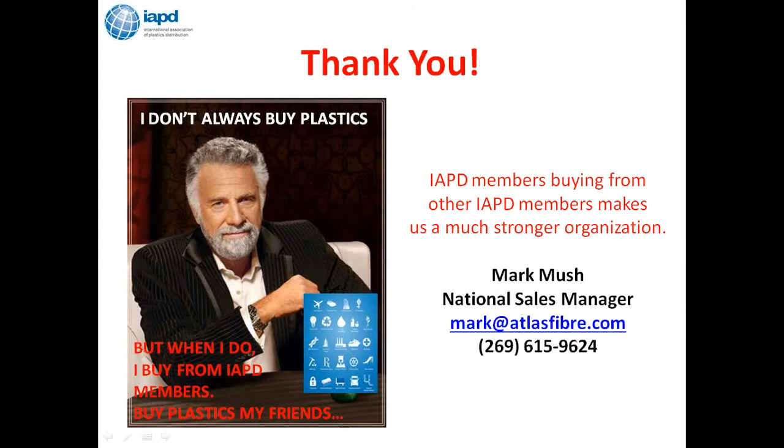Why can you not broach thermosets? Unlike a thermoplastic that is somewhat pliable and movable, and you can squeeze it under pressure, once you've made that thermoset, it doesn't move very well. And a broaching operation is a displacement of material, so it would be like trying to broach something that was very, very hard, and you'd wind up just destroying the material. Unlike trying to put a broach in a piece of nylon or Delrin, where it's going to actually push that material out of the way and create the form that you're looking for, it'll probably fracture a thermoset if you try to do that. Okay.